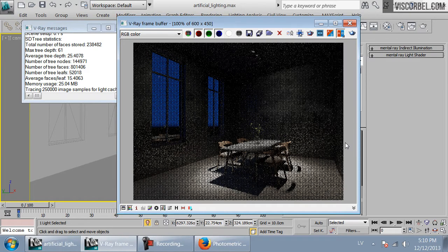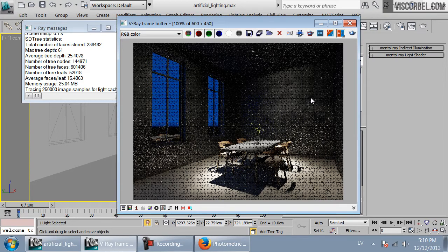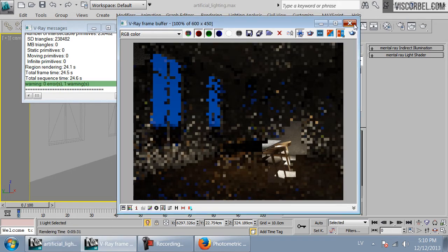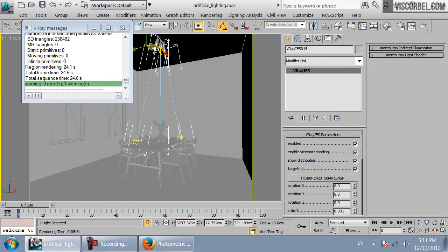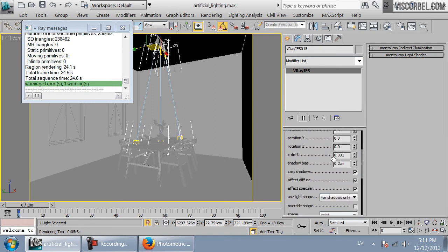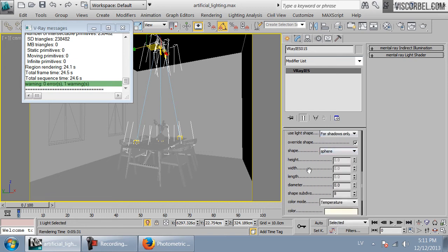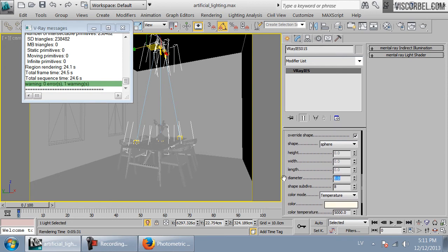And this is a cool effect to use for these dark interiors where you have dark walls, dark ceilings, and maybe some sort of piece of furniture or any other accent piece brightly illuminated with some spotlights. I think it looks pretty cool. Okay, I'm just gonna increase my shadow softness by creating a spherical area shadow with small diameter.